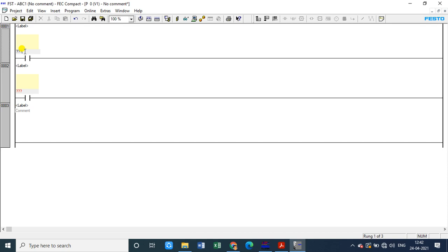And on the output side, because the PLC that we will be considering will be one device which will be having input module and the output module. So on the input side we are connecting like this, and on the output side 1m1 coil will connect to output port 1, 1m2 to port 2, 2m1 to port 3, and 2m2 to port 4.